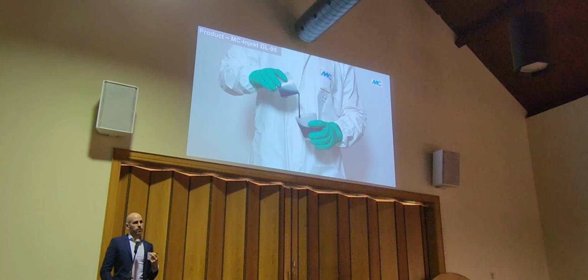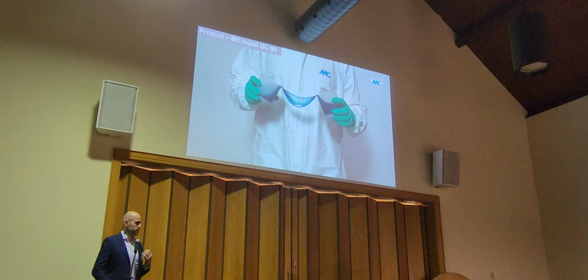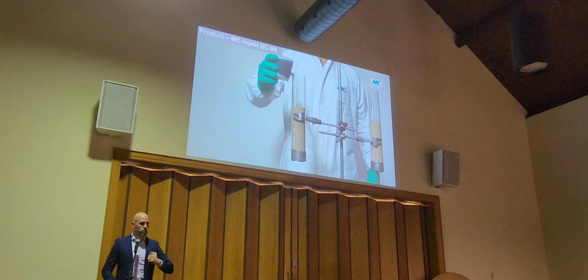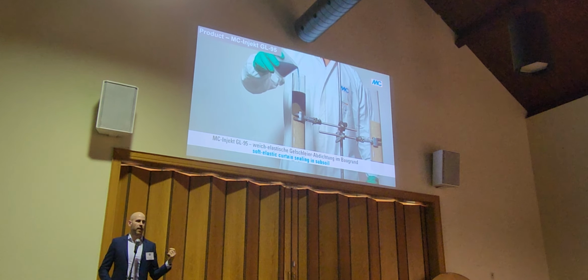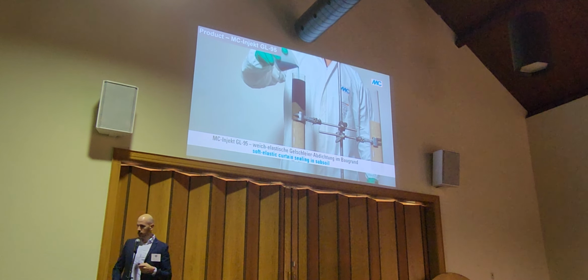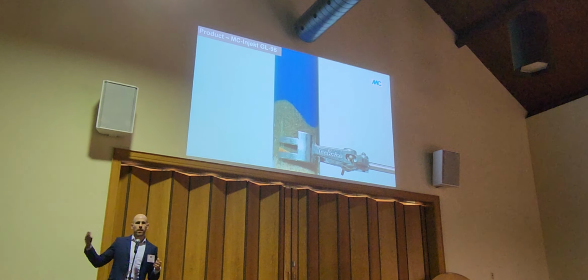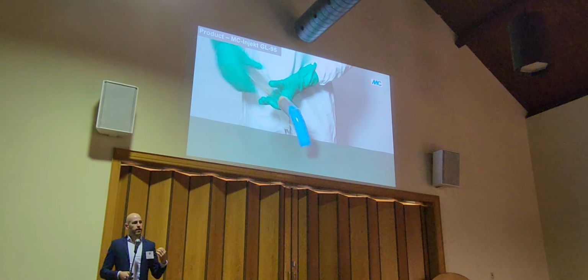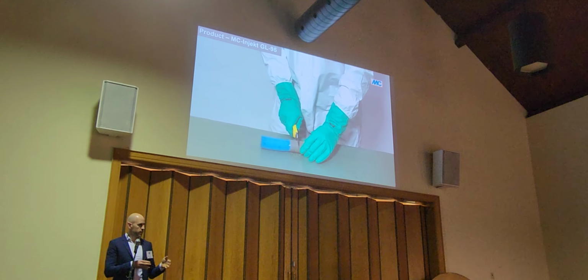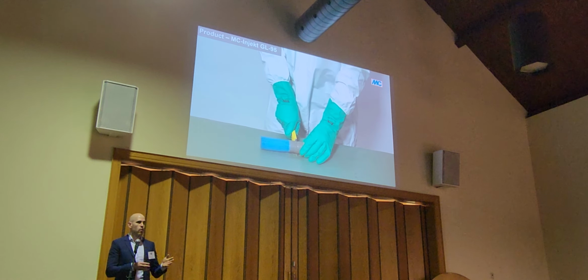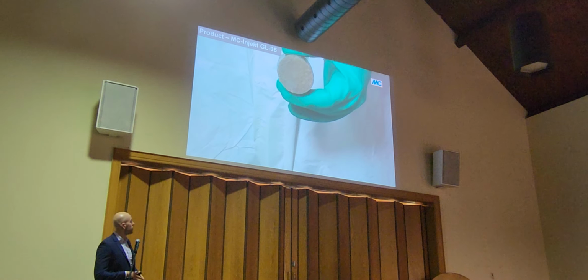Their question, when I spoke about gel, they asked, okay, come on, I cannot excavate in gel. I need strength. I need something which is rigid. And I said, okay, come on, let's do the trial and you will decide if you can excavate or not. The good thing of this gel is you can control the reaction time from a few seconds to several minutes, and once this so-called gel point is reached, it gets from fluid, like 5 millipascal seconds, like water, to a jelly stage where it's not flushed away anymore.